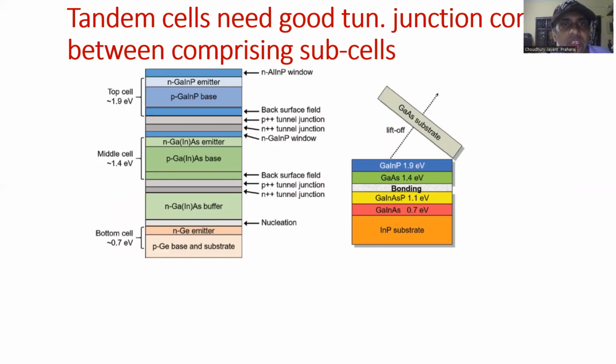More details about tandem cells. The tandem cells need good tunnel junctions. So here we show a typical tandem cell configuration. This is actually in a different material system, but it looks kind of similar in the indium gallium nitride material system. And we showed some of this typical diagram for the indium gallium nitride system in a previous slide. But as you can see, we have these P++, N++ tunnel junctions in these materials that go into determining the interfacial characteristics between these subcells. And so we have voltage drops between these subcells, and we need to make sure that these voltage drops are small so that we get the maximum power conversion efficiencies.